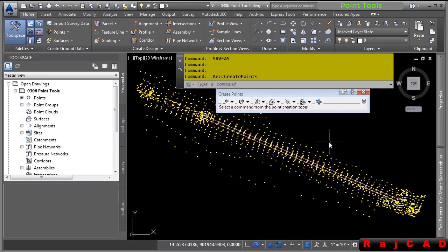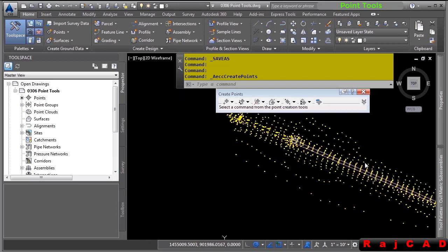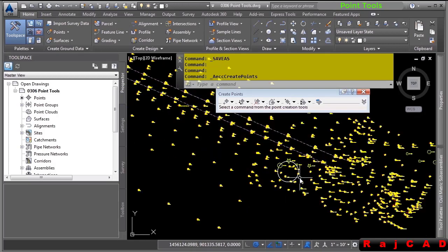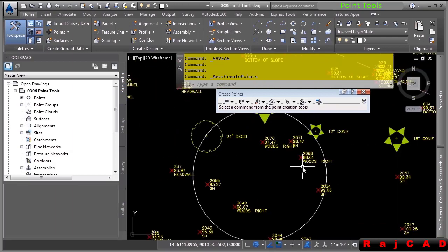Let's go ahead and leave the point number set to 5,000, and we'll just click on that to minimize it. And let's just create a basic NEZD point. Let's go ahead and zoom in where we're going to create the point. A circle has been created for you. And let's say we have a tree that the surveyors forgot to pick up, but they have it included in the fieldbook file. So this will just be a miscellaneous point. Let's go ahead and click on the miscellaneous dropdown here and click on Manual.